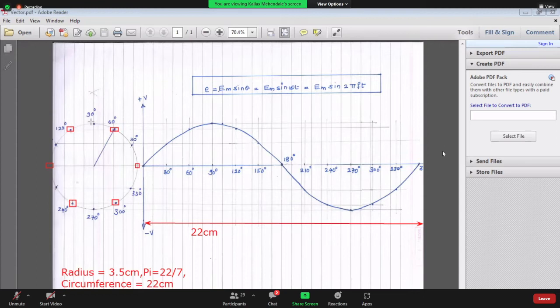Then, this is obviously the 90 degrees line. So I put my compass over here, cut an arc over here and over here. Then I put the compass over here, cut an arc over here and over here. As you can see, I divided the circle into 12 equal parts within no time using minimal geometrical equipment. The idea of doing this is that in the exam, time is going to be essential. The less time you use, the more time you'll have for your thinking and writing.